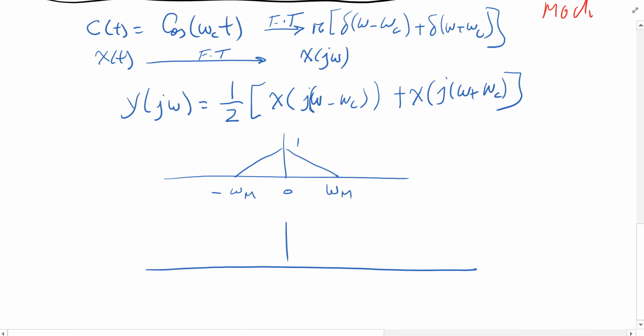So this was X(jω), my signal bearing, and my carrier C(jω) would basically be an impulse. Hopefully the impulse would be way out there. Let's do it properly, because the other thing to really think about is that you want your ω_c to be much larger than the maximum frequency, otherwise you're going to have aliasing because the ends will overlap each other.